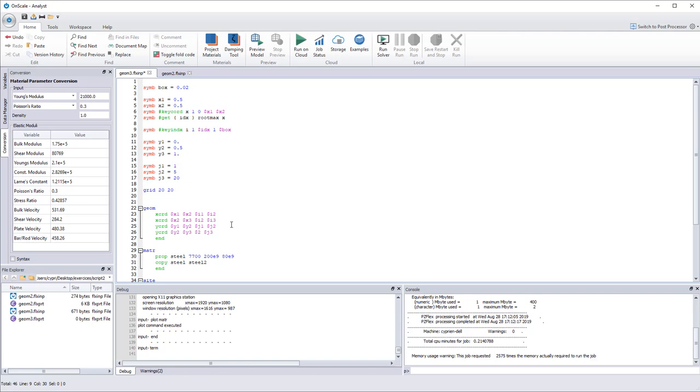So now I will have much more than 20 elements for my grid. So what I need to do is generate the grid in function of the value that will be created by those macros. So for that, instead of 20, I'll put the value $I and $IDX. So why do I write it like this? I write it like this because the symbol language works like this.